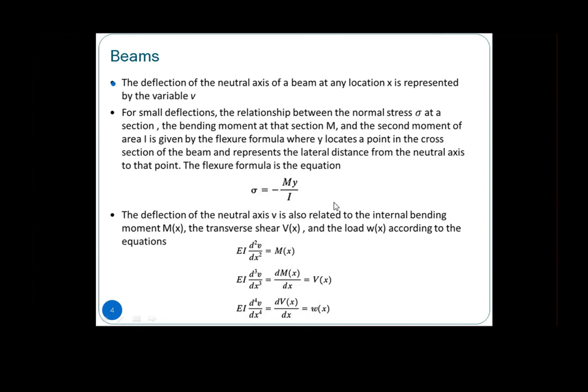At the same time, we also build on beam deformations. We also build the relationship between the loads, which generate the transverse shear force. From there we have the moment, then the slope or rotation, theta, then v, or what we call the deflection. That is the relationship here.